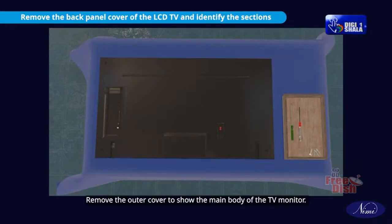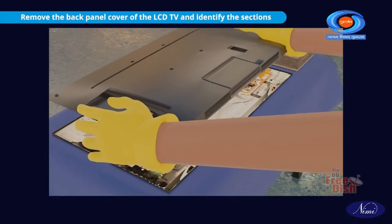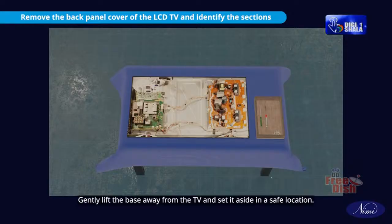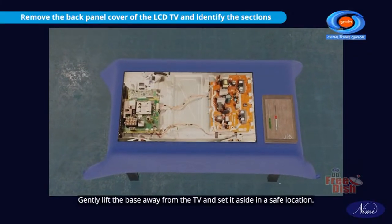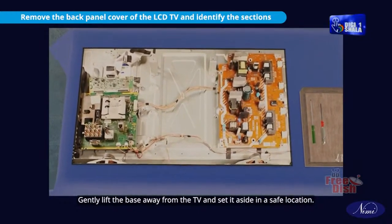Remove the outer cover to show the main body of the TV monitor. With the screws removed, the base should now be detached from the TV. Gently lift the base away from the TV and set it aside in a safe location.